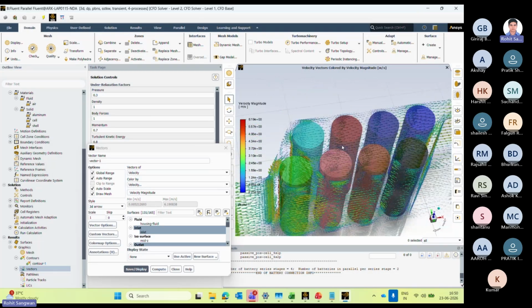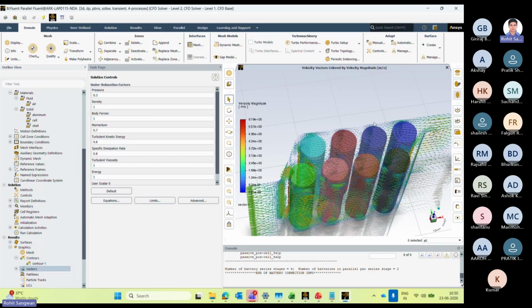Okay, so if you give virtual connection, it will help us to have better battery thermal management as compared to direct connection. Mostly in cylindrical cells, we give virtual connection. That's why there is an option of virtual connection in cylindrical cells. Okay, so if we use battery model, that will give us more advantage and more accurate result instead of directly giving only heat source. We can use heat source also, that is also equivalent.